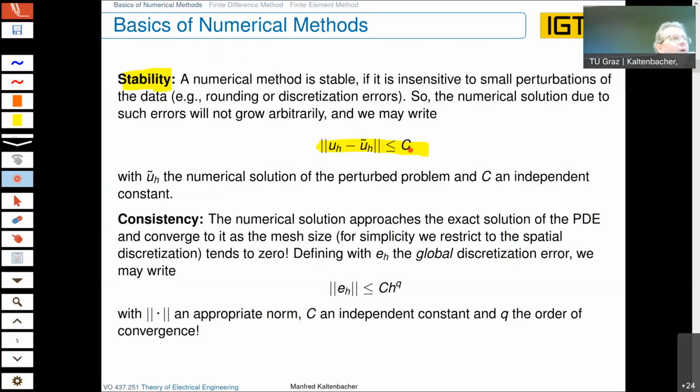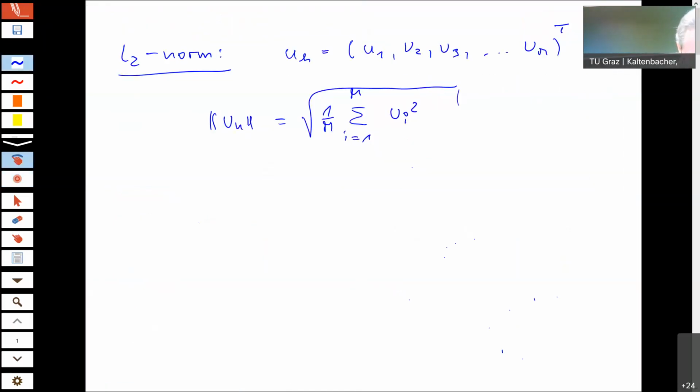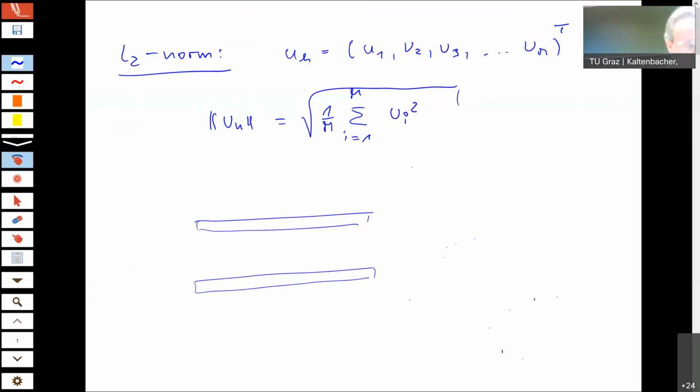Even with a simple setup like this, you have here the top electrode and the bottom electrode. And you look at how your charge distribution is: it is not constant along the electrode, along the bottom surface of this electrode. You will see an accumulation of charges towards the corners here. It will be somehow constant here, but it will increase towards the corner.